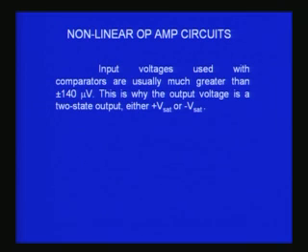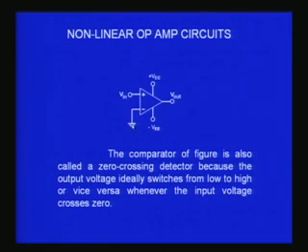So, you can see I can detect two voltages within a range of 280 microvolts, or to be precise plus or minus 140 microvolt. That is the basic principle of the voltage comparator. Now, you can see the circuit once more: one input is connected to the ground, therefore, this is a 0.